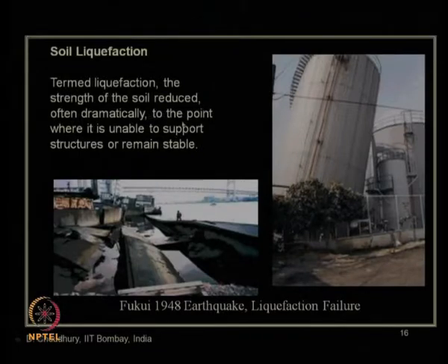So, in that condition, obviously, whatever structure is constructed on the soil will no longer stand on soil, but it will stand on a fluid, by the conversion of this soil through the full liquefaction process during an earthquake. And that is why that fluid cannot further take the load of the huge structure which is constructed on it. So, finally, the entire structure will get damaged or collapsed.